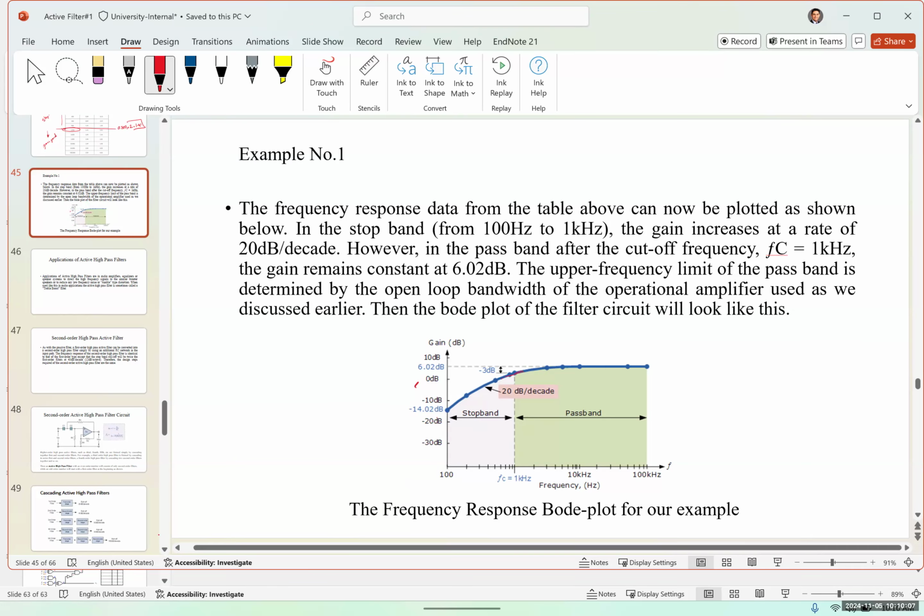It has a cutoff frequency, but the stop band has a very smooth slope, and it decreases 20 dB per decade, so it's not a lot of decrease. If we need a sharper filter that looks like this and filters any unexpected frequencies, then we need a higher order filter.